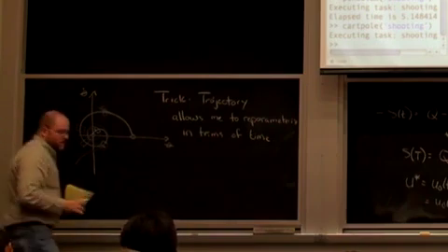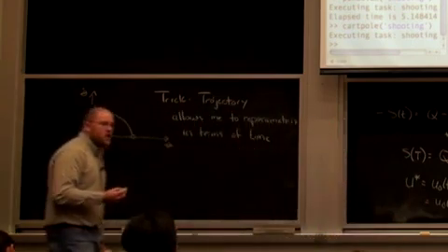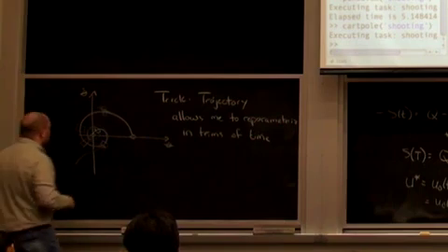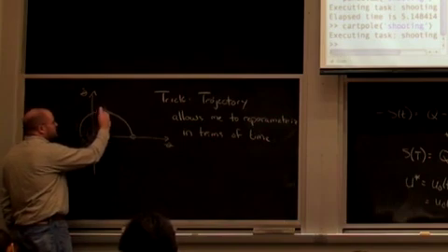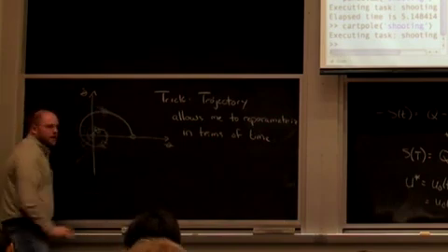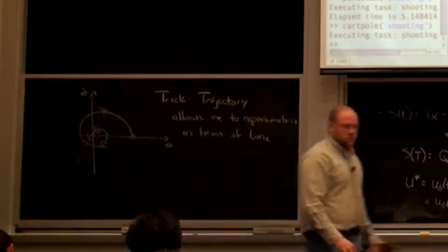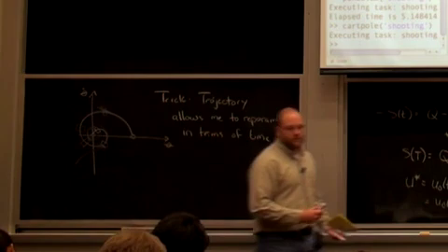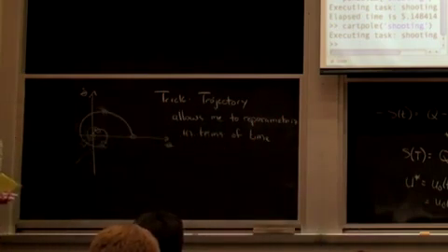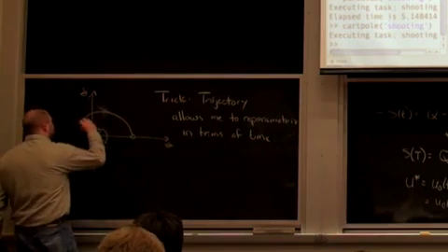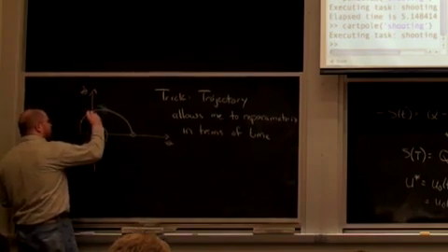Here's the question. What happens if, instead of just changes in initial conditions, I have disturbances that push me off the trajectory? Well, that's okay. That's no different really than a different initial condition. They'll come back on here. What happens if I have a disturbance that pushes me along the trajectory with this controller? Let's say I've got the helpful disturbance, which, when I was right here, happened to push me right to there.